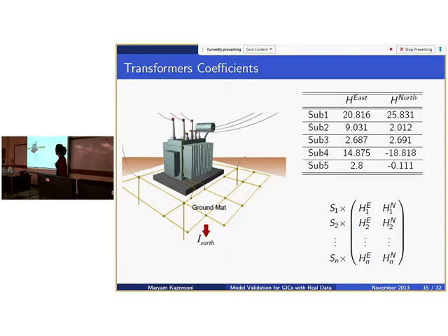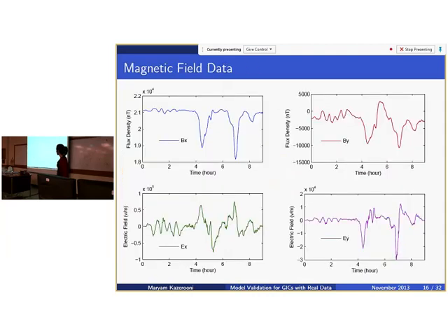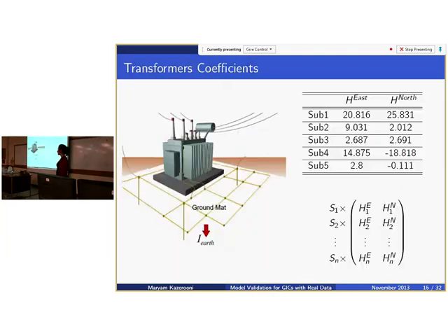And yeah, I was saying that these scales associate with the ratio of the actual grounding resistance to the assumed grounding resistance. I have a quick question. You wanted uncertainty only on substation grounding resistance. Do you have accurate transformer grounding resistance from ETC, or is that also derived from the Eastern Interconnect model? So these scales, we actually can estimate based on the GIC measurements which we have.